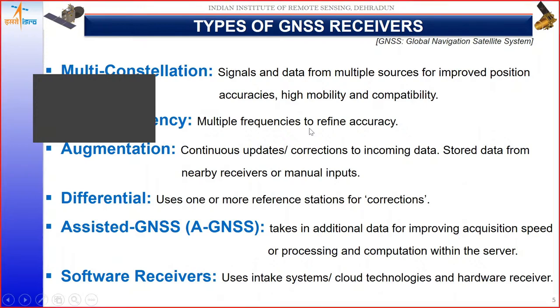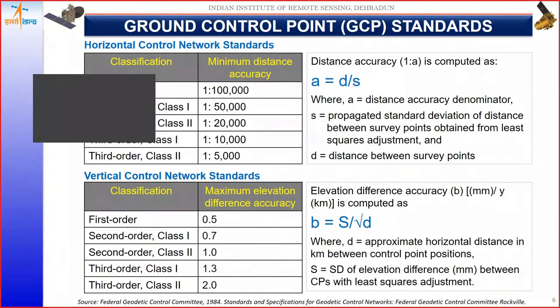Okay, so these kinds of receivers are available. Then based on your need, as I suggested, if you are looking for very high resolution, and you want to acquire ground control points for georeferencing of high resolution satellite data, then you require DGPS based control points. If you want to rectify your cadastral maps, again you require the differential (DGPS) based control points.